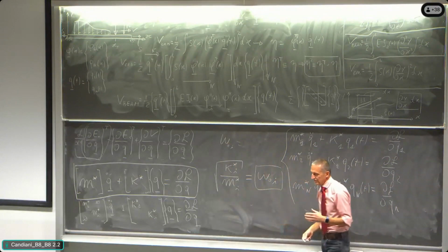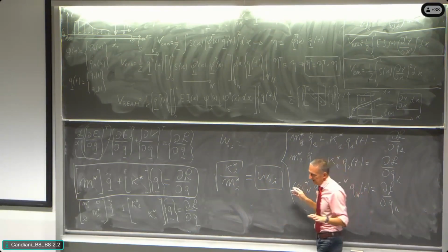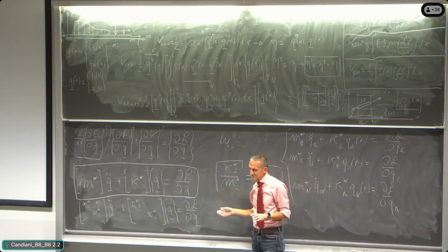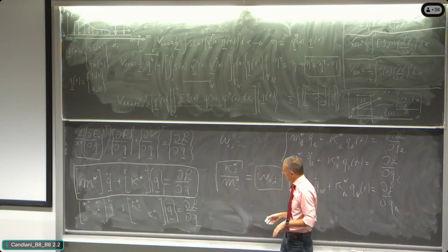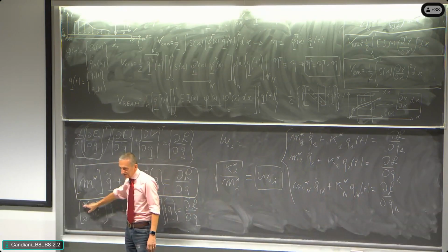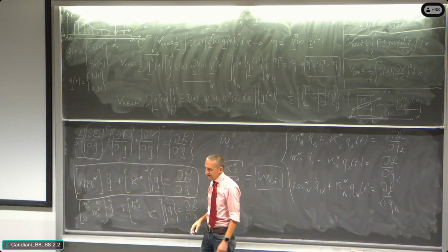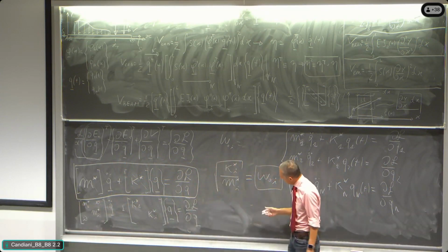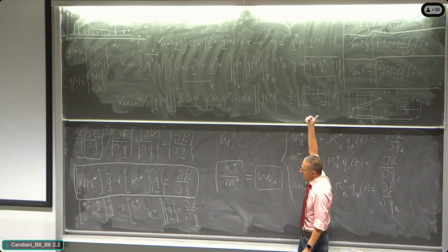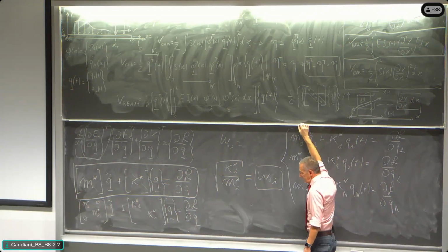In the demonstration of the orthogonality, it's possible to demonstrate analytically, without making any calculation at all, that the out-of-diagonal numbers of those matrices are 0, and that the ratio of the non-zero element i of the stiffness matrix divided by the non-zero element i of the mass matrix is analytically equal to the square of the natural frequency that was found at the very beginning of the story, making the solution of the free motion of the system.